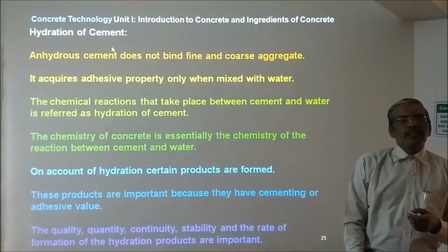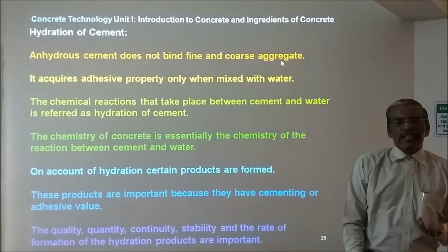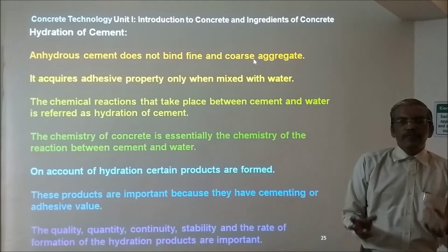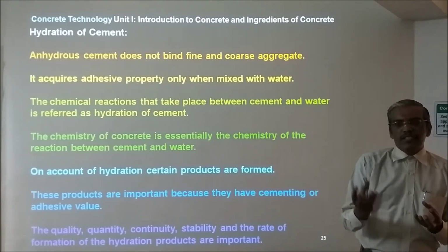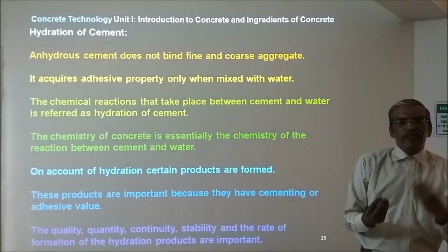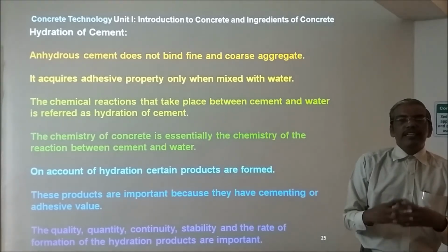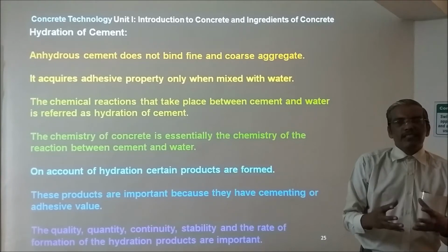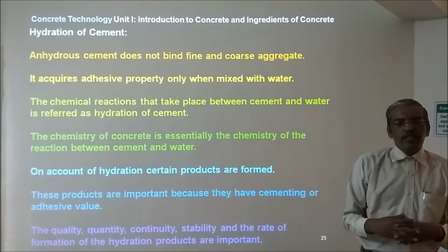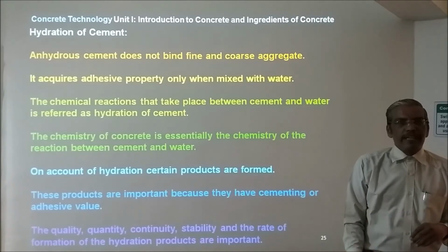Anhydrous cement does not bind fine and coarse aggregate. So if we take the cement, fine aggregate and coarse aggregate, and mix them in dry condition, that is anhydrous cement, they will not bind together. So for the binding purpose, water has to be added.